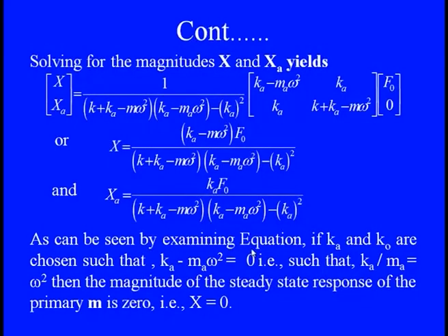So, this is the solution we can get, even the eigenvalues or the eigenvectors for such systems. When we are dealing with these things, we know that we have a clear amplification ratio, or rather the mode shape. This is absolutely dependent on the stiffness, k plus k a minus m omega square. At the same time, whatever features you see are coming in the denominator, like k a minus m omega square and minus k a square.